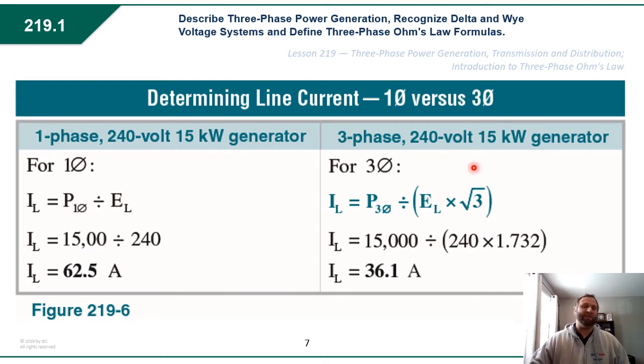Guys, you wouldn't believe how many Ohm's law formulas you're going to see on this test. If anything, I would definitely camp out in understanding three-phase Ohm's law formulas. Go back, work on your homework a little bit from lesson 219, 220, 221. You'll need to be familiar with three-phase Ohm's law and incorporating the square root of 3.